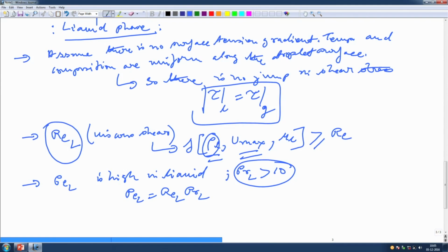So, the Peclet number is usually high, sometimes greater than or equal to 100 in many of the cases that we are going to consider. When the Peclet number is that high, that implies that convection is much more dominant than diffusion. Essentially that is the significance of the Peclet number.